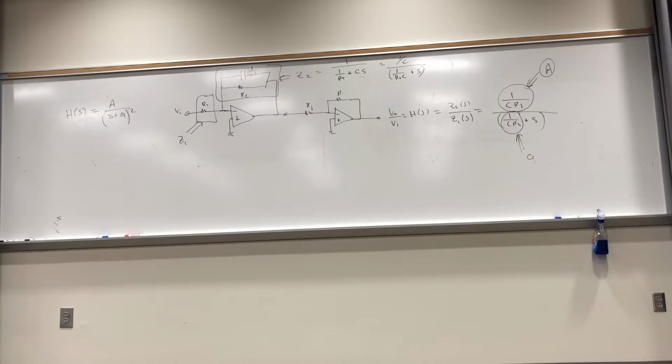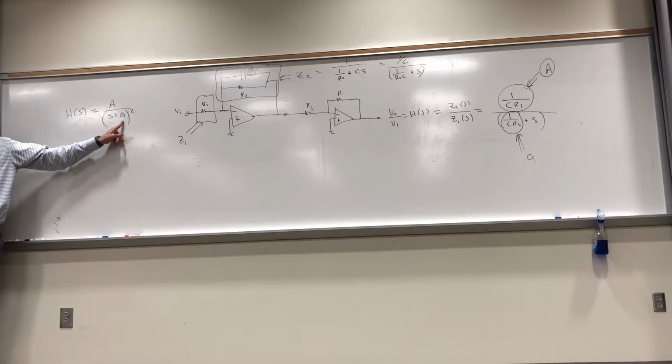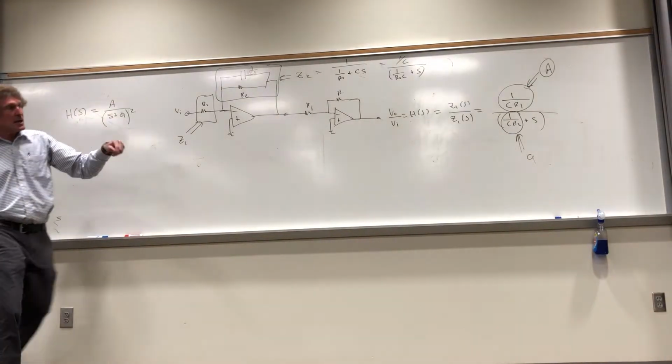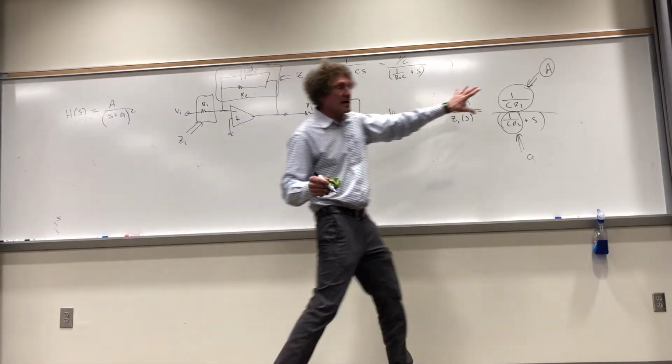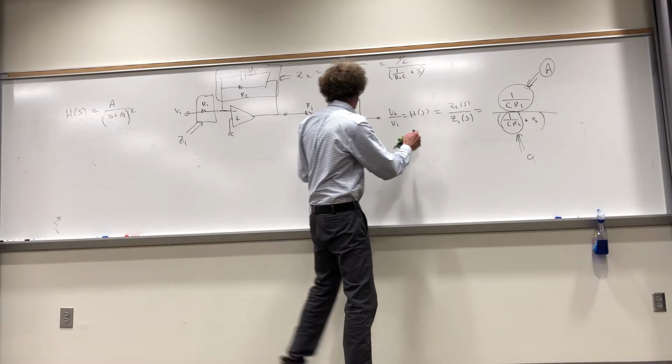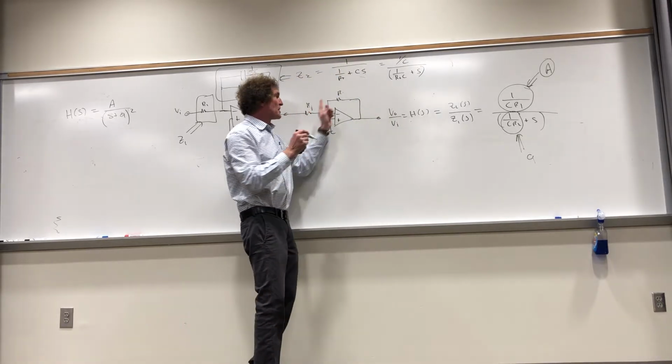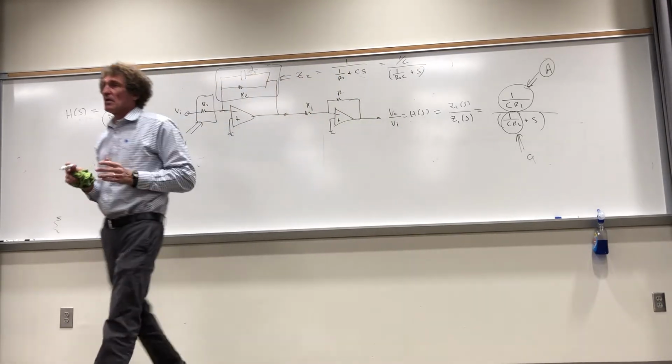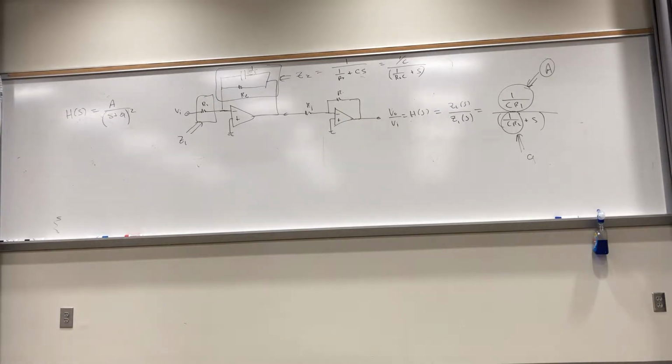You have a range of capacitors and resistors usually to choose from. You don't have a continuum of values. So what you do is always get that lower time constant here exact. All right, you make that work. Then up here, you may not be able to make this work exactly. So in order to make it work exactly, you're going to scale these two resistors so the effective gain of that will get you the constant you want. That's the way it always works.